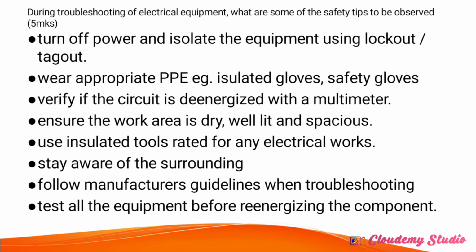By turning off the power, you will be in a good position to prevent yourself from potential hazards. And after turning off the power, you isolate the equipment or the place that you are working on from the power source. If you are doing an electrical installation and you discover that you have gone to a certain site and the lighting system is faulty, but the socket system is okay, the first thing that you'll have to do is turn off the power from the main switch.